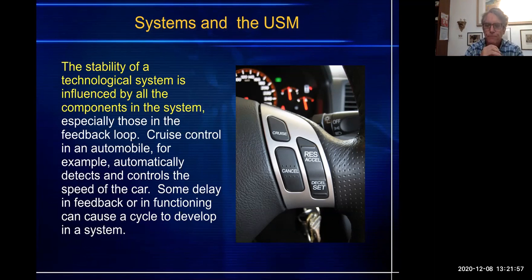We're going to stop here, but cruise control is interesting because cruise control only limits the accelerator. It will keep you at a constant speed going uphill, and it will stop accelerating as you go downhill, but it does not activate your brakes. It does not actually keep your vehicle only at 30 miles an hour. When I am going down a hill with cruise control, I can go 35, I can go 40. But that's because the feedback system is not controlling braking.